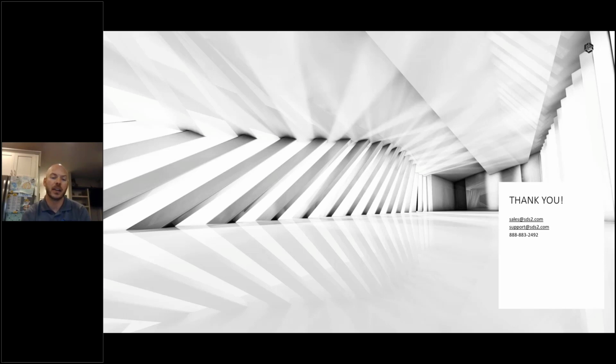And then if it's a really small change, the user could go update the drawing themselves manually and clear that mark for detailing flag manually. Otherwise, if they detail the member again, SDS2 is going to update that accordingly based on the new model information. And there's a couple options when you detail to preserve all the user changes that you may have made previously to that. That will help reduce the rework that might happen by regenerating that detail.